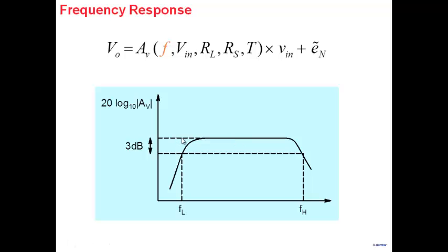And what do we call this region? Mid-frequency region. Obviously, it makes sense. At lower frequency, gain is changing. At higher frequency also it is changing. There's a mid-frequency range where gain is relatively constant with frequency here. So when I talk about gain 100, 200 or whatever, I'm talking about gain in this region. So whenever we talk about gain now, please understand, even if it is not said, it is the mid-frequency gain. Mid-frequency gain here.